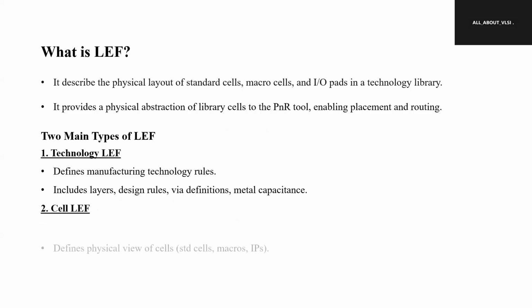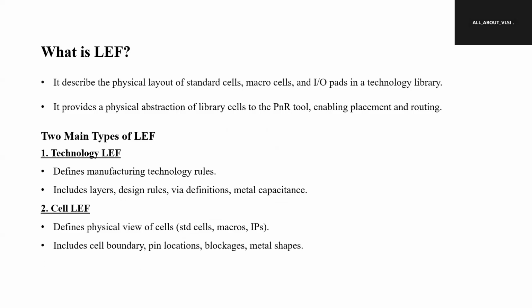And the second one is cell LEF. It defines the physical view of every standard cell and macro. It includes the pin locations, and it also contains blockages and keep-out margins. All this information is presented in cell LEF.